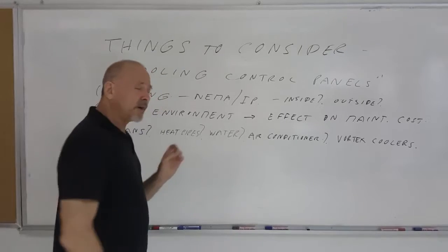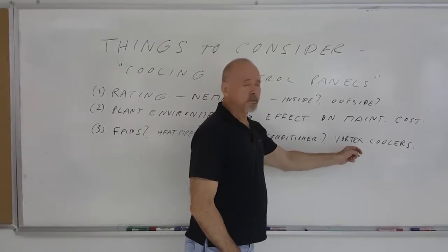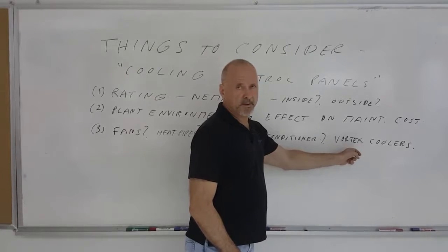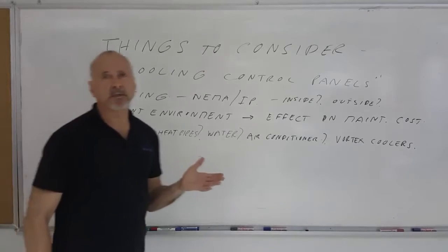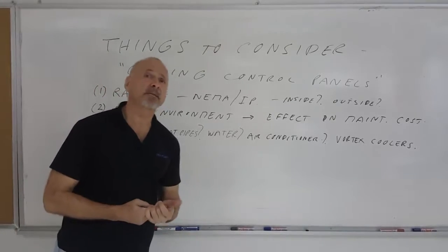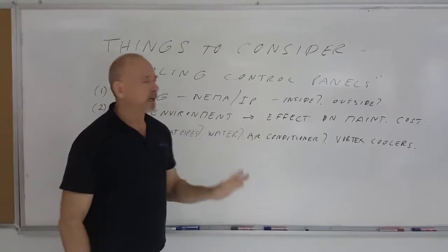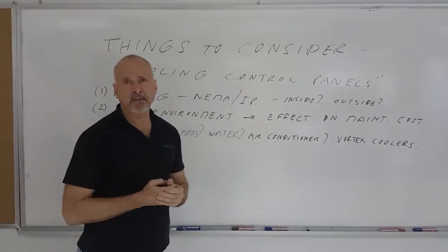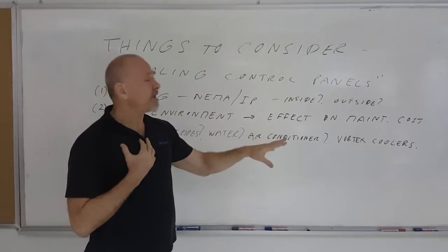So when you get to a very, very dirty environment, you then have to really consider using compressed air operated VORTEX coolers. The VORTEX coolers have virtually no maintenance. They're not subject to vibrational damage, no chemicals, no condensate is produced. They can be put on a control panel and just left to run. And there are other advantages as well. But basically, it's the maintenance saving that really shines.